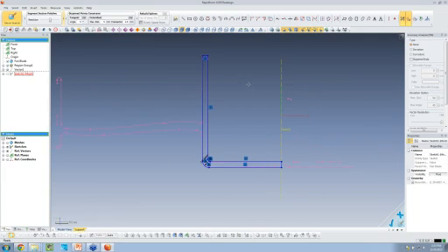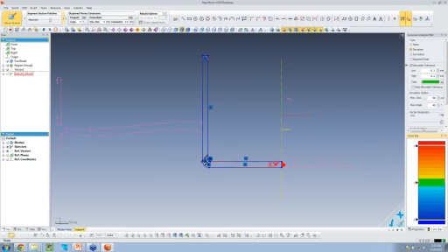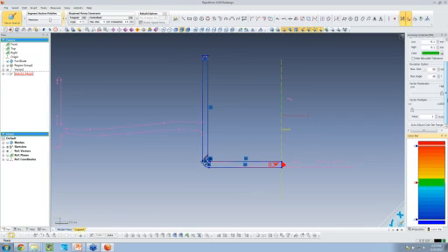So I can also do a little bit of checks here as well. How well did I do? My question is, I'm starting to do this, and how well is my part actually coming out? We have what I call the accuracy analyzer here. It's an ever-present accuracy analyzer. So I can look at my deviation, and you can start looking at a deviation plot, and how well that scan data fits the curve or features that I just made.